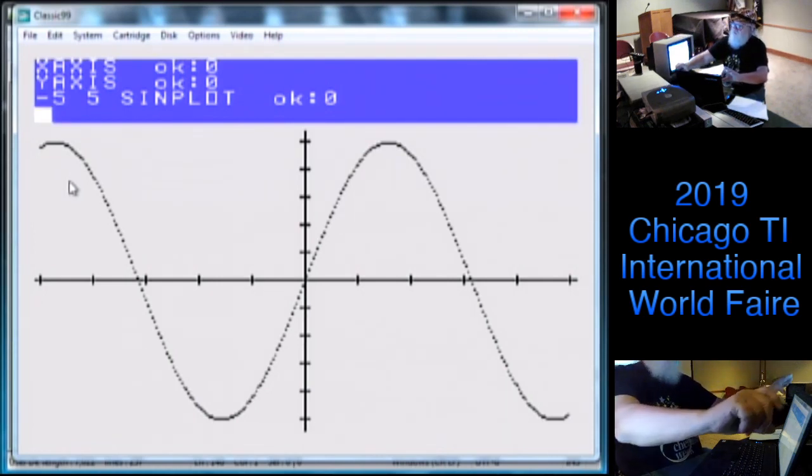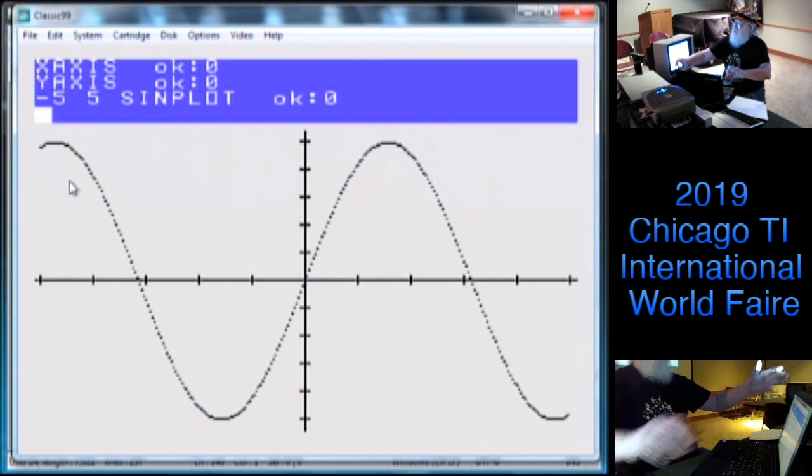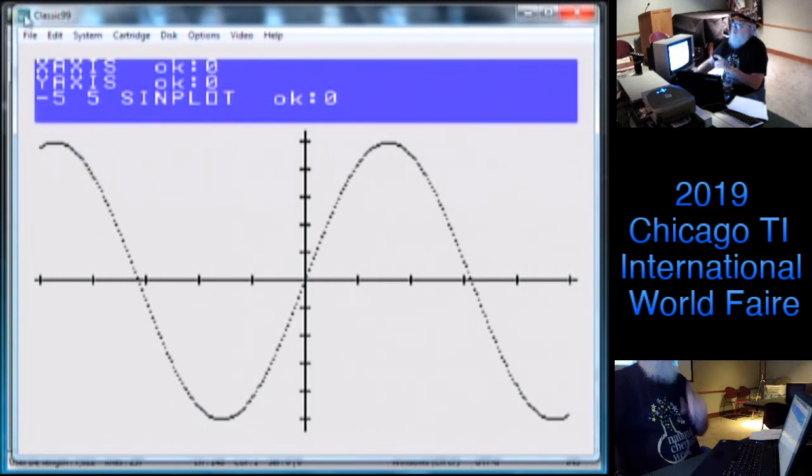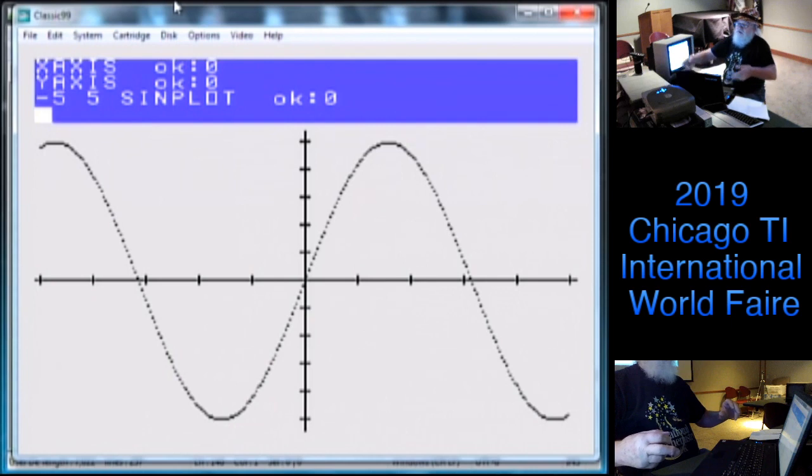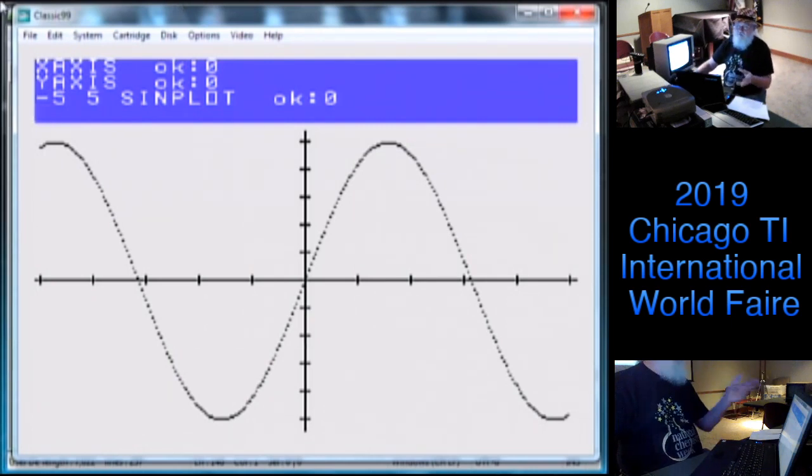The first third of the screen, you have 256 unique characters, but the clincher here is that you have 256 unique positions now, because you can have one character per position that doesn't repeat anywhere in that 256 byte character block. And with the second third of the screen, you have another 256 characters, and the third, another 256.